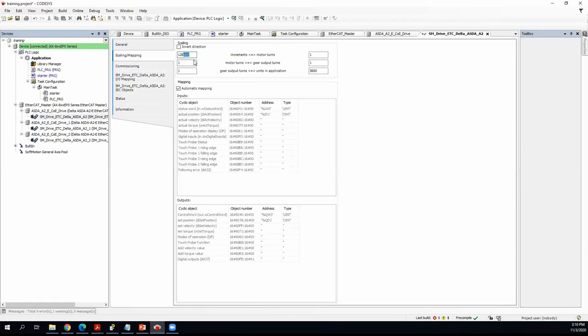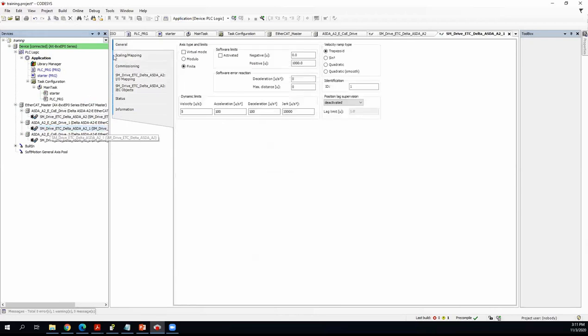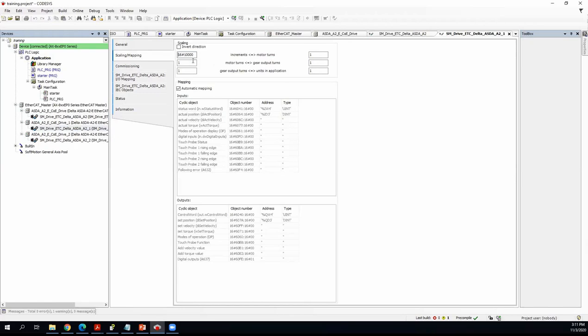Yes. Thank you, Vladimir. Yes, we missed a zero. It should be 1,280,000. Yes, true. This is the resolution of the servo, and for the rest, we can use the same conversion. So this is the increment number for the servo. It's defined in the factory, so you cannot change it.